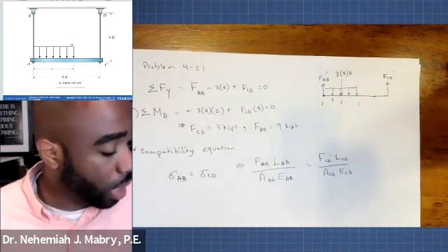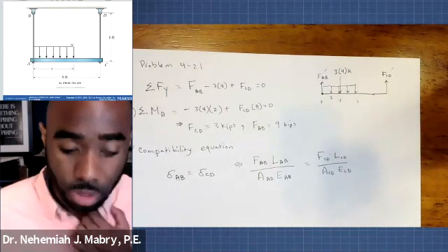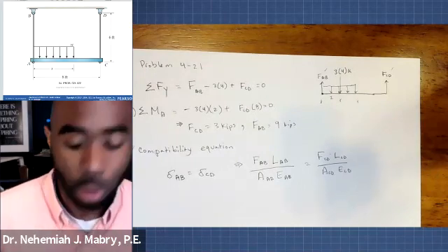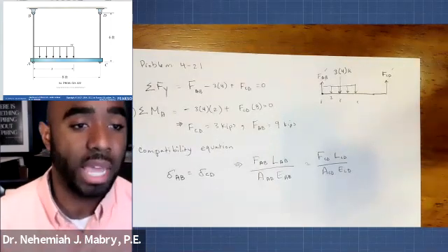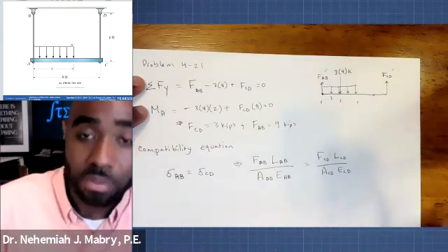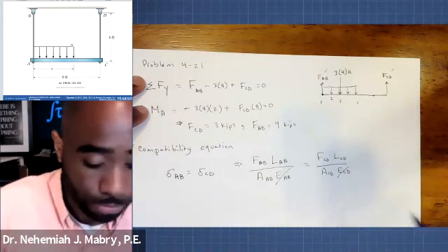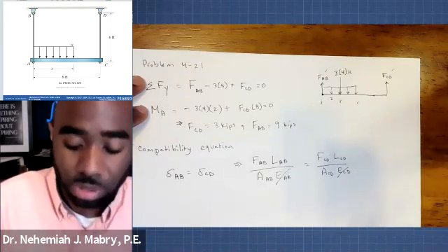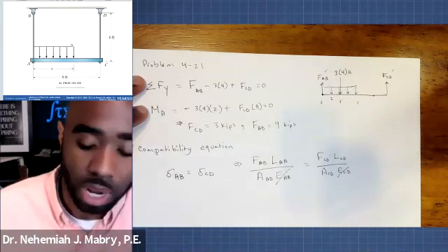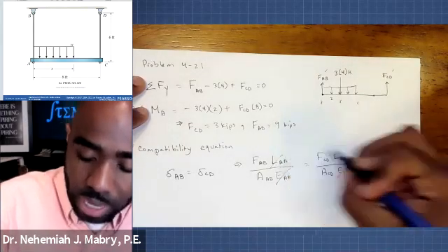So we're in luck for a couple of things, right? We are in a good position for a number of things. When we look back at our problem statement, we see that both steel beams are of the same material, A36 steel ties. So that means that E, the modulus of elasticity, will be exactly the same, and so we can go ahead and cancel these out. Another thing that we see are exactly the same is the length of these rods. The length of these rods are both 6 feet. So we can go ahead and cancel that out.